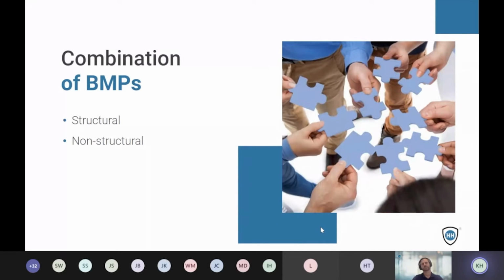Policy is great, but maybe you also have an engineering control in place that you have level indicators on your tank so that you know if anything has leaked. And you also have a spill kit available so that if something does spill, people are able to clean it up quickly. So it's that combination of things that is going to help collectively to keep things out of the waterways.